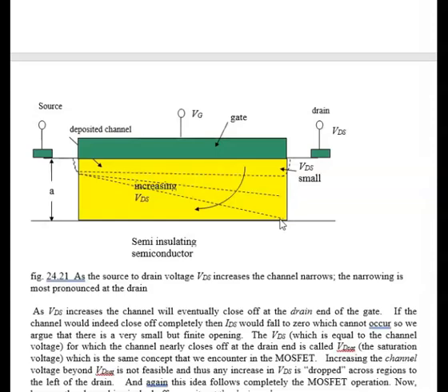The only difference being that in a MESFET we have a deposited channel here, which may be, oh gosh, off the top of my head, anywhere from 1,000 to 3,000 angstroms, whereas the inversion region width we don't even talk about. This thing called T inversion in a MOSFET is a quantum well, and it's just at most a few tens of angstroms. So that's really the only difference here.